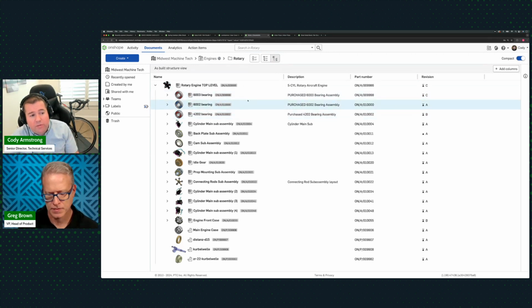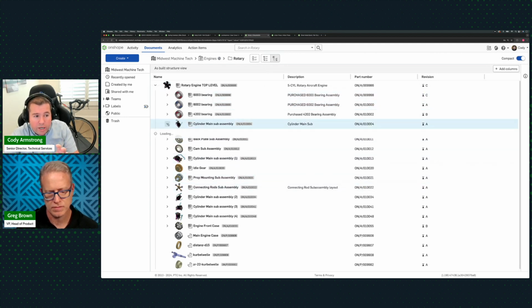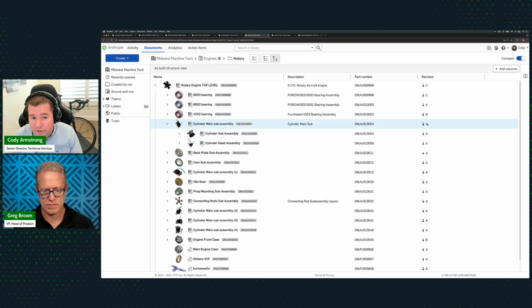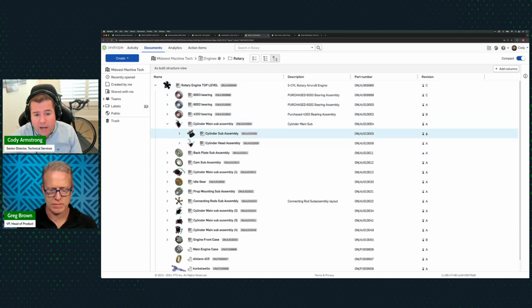And so I can't stress this one enough. If you're navigating today using list views and struggling to find the right folders and directories that all the various components exist in, try turning on structure view and just seeing how you navigate it. Because now I'm navigating my design based on its structure, right? And more importantly, the latest as-built version of this, the latest released version of this. And so it's important to stress you're looking at the latest released version of this product and all of the released parts and subassemblies that exist within. You can see my top level is at Rev C, but I have a handful of releases that are Rev A, Rev B, and so on.